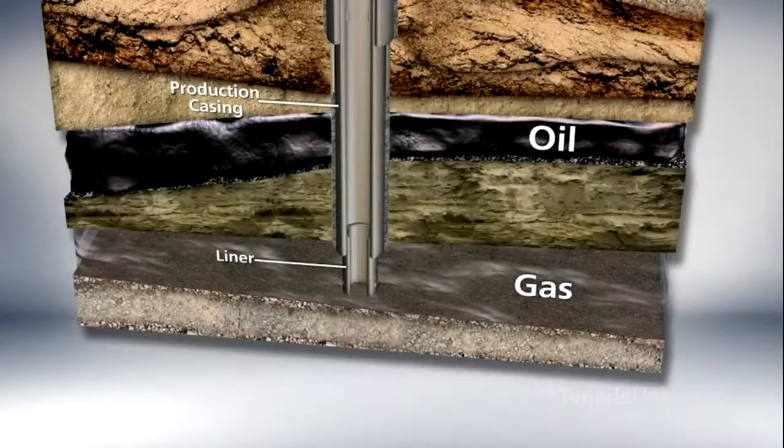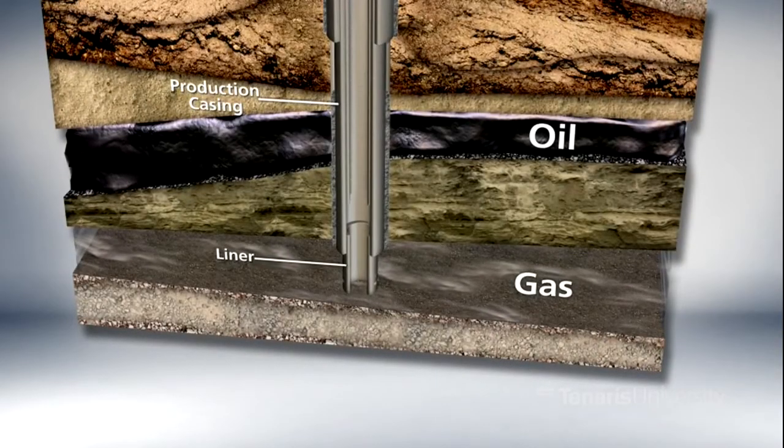This means that at a later stage during drilling, another string will be set between the drilling liner and the tubing. And on the other hand, we have the production liner. This is a liner set in front of the productive interval of the well, and as it is normally facing the tubing, it has to withstand all the conditions arising from the fluids in case of a failure or damage in the tubing. And finally, we have the tieback.